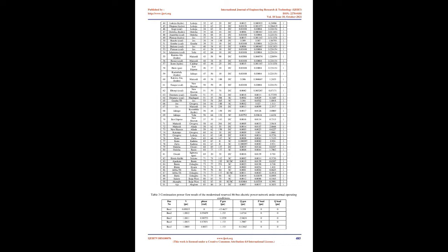The Jacobian matrix of the conventional power flow algorithms becomes singular at the voltage limit. These conventional power flow algorithms are prone to convergence problems at operating conditions near the stability limit. The continuation power flow analysis overcomes this problem by reformulating the power flow equations so that they remain well conditioned at all possible loading conditions.